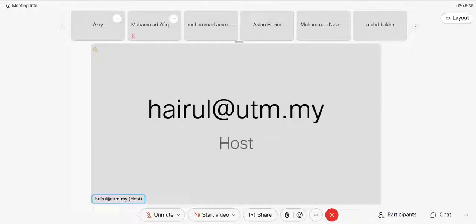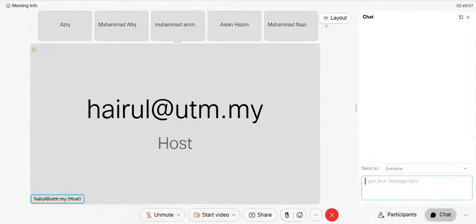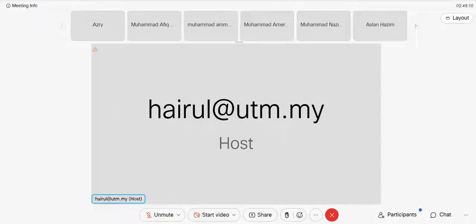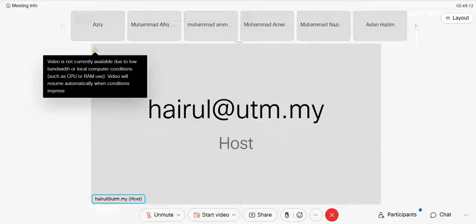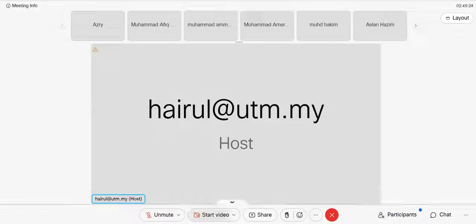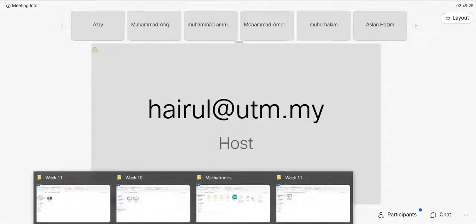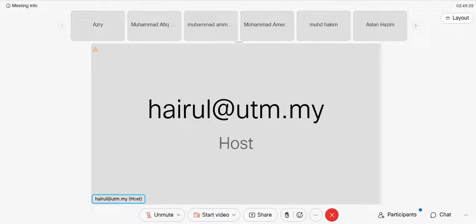Okay, in this sample problem, your bending stress is FT times diametrical pitch over B J, times KV, KO, KM. So the only unknown is FT, and your bending stress is in terms of variable FT. Your SN is CL, CG, surface factor, KR, KT, KMS, all times SN prime. You will get this in KSI in English units, where KSI is 1000 PSI.